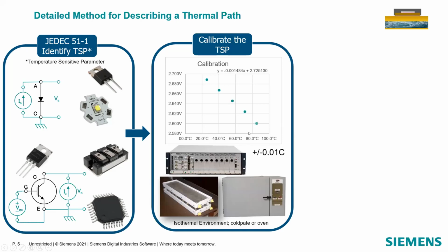And as we change the ambient temperature, we record the corresponding voltage change at steady biasing. This will give us a relationship between the voltage and the temperature, essentially turning our semiconductor into the temperature sensor itself. This can be done with high accuracy and high resolution. You see the 0.01 degrees Celsius value for the resolution of our systems.